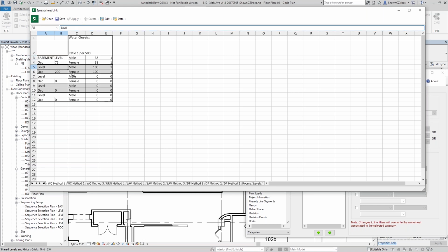Now I'm going to do a little bit of manual work here because I'm going to copy and paste this here and say index my levels for the second level in the list. I don't care what the name is, just pull the second name. I'm going to come down here, do the exact same thing, paste, use the third thing in the list, so level 1, 2, paste, I think I did 3, 4, there we go, and then 5 here. And you could do this as many times as you needed to. I'm doing this in a very manual way. There's, of course, more automated ways of doing this.